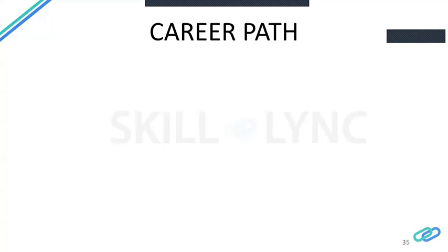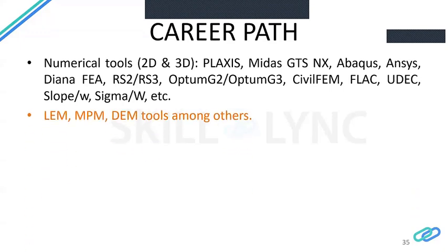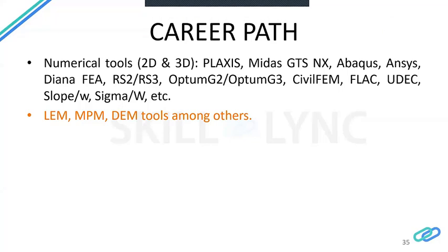However, if you want to proceed with the design part of foundation engineering, you have to develop certain skills, both soft skills and hard skills. Regarding the soft skills, you have to develop numerical analysis skills, dealing with different software and different numerical tools. This is a list of some of those tools. And you have to be familiar with methodologies other than finite element modeling, like limit equilibrium and the material point method, as we have stated earlier. And you have to know the limitations of each tool in your software.